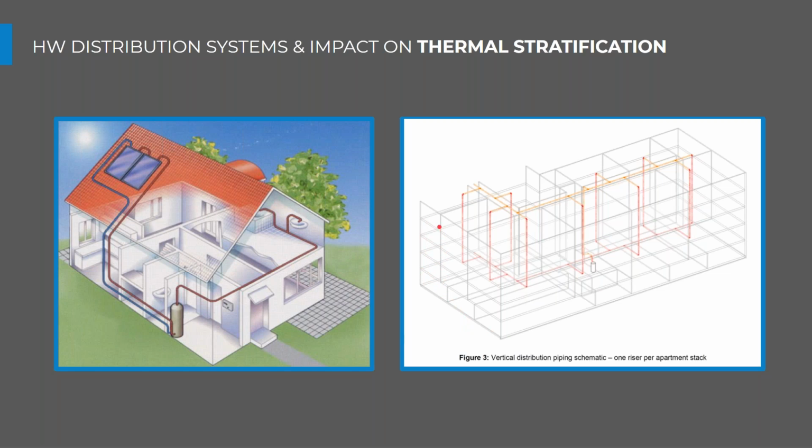But please raise your hand if you've been working with an architect and they've given you a building and all the apartments stack. I can't see your hands, but I'm sure that there weren't that many hands raised. We typically have variation in our apartment design, and that might mean that this unit and the unit above it don't stack on top of each other. That results in more risers typically, or more piping to serve that riser as it's going to jog